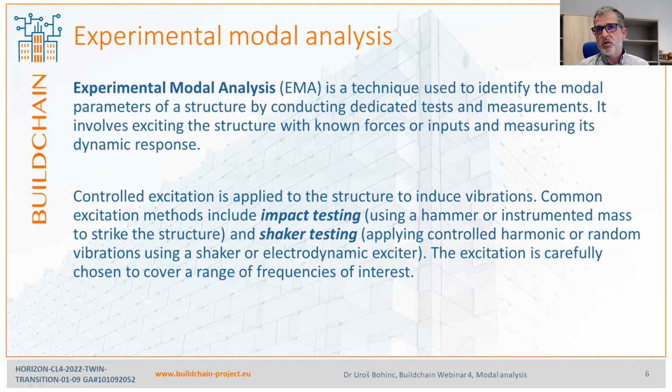So this is the controlled excitation that I talked about. So using a hammer which has a device, a load cell installed, which can measure exactly the force applied to the structure, can be then used to excite and also to measure the excitation of the structure. That can be done also, as I said, with a shaker, but using a shaker is more cumbersome.